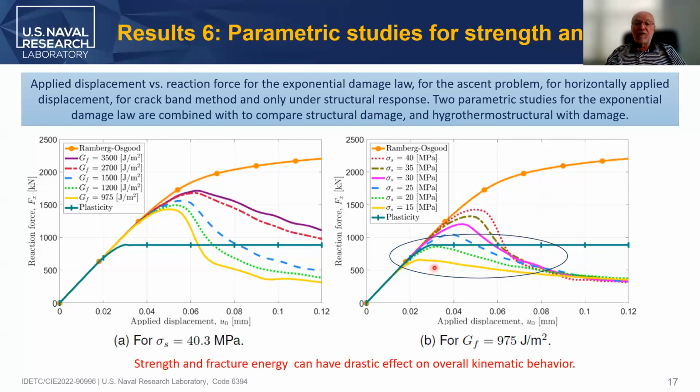We see that for certain values of the strength, we can get a deviation from linearity much earlier than plasticity is yielding with the damage model, which says that if indeed there is a dependence of the strength on some parameter that relates to the performance of the plane, then designing for elastoplasticity is no longer the conservative choice. There is a much more dangerous situation for the yellow and the green lines that we need to account for.